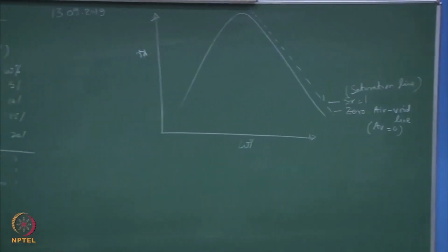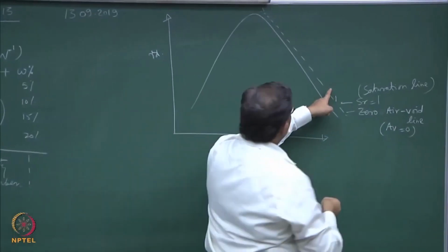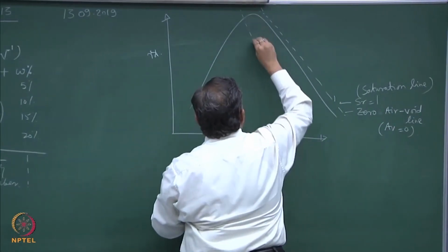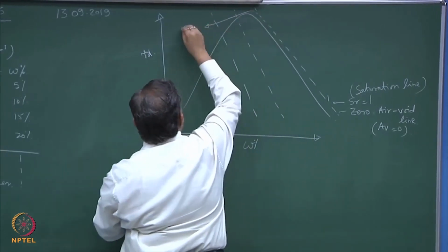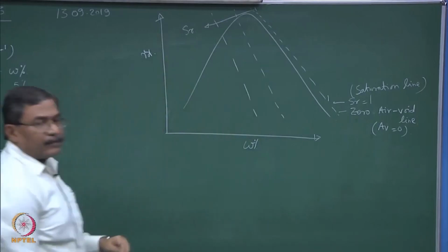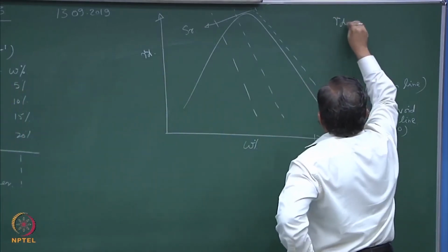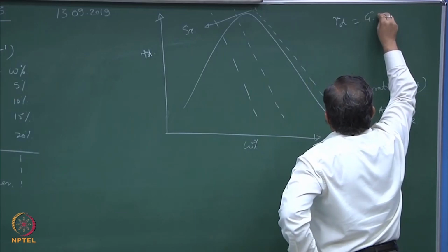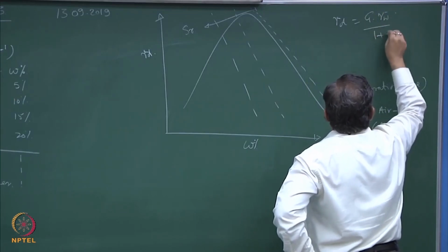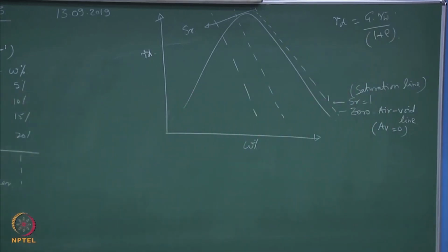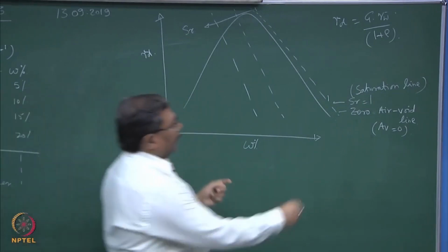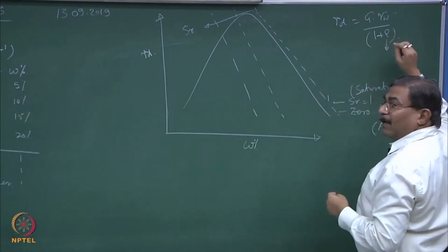Did you get the answer to your question? So, saturation is somewhere here. If I draw a line which is like this, these are the contours of saturation. You know the relationship gamma D is equal to G gamma W over 1 plus E. It is not going to be of much use to me if I try to interpret the results using this equation. Why? Because there is a foreigner sitting over here in the form of E. So, I have to get rid of this E. How can I get rid of this E?